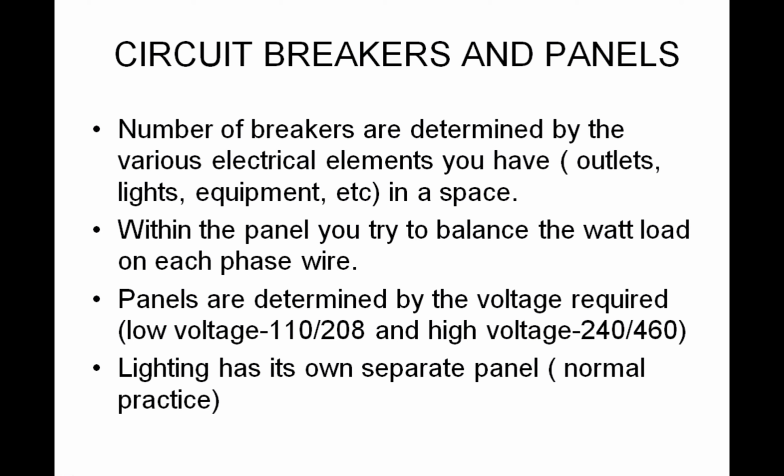And that's also so that if we need to work on equipment or systems, you're not working in the dark. If a system trips, like your HVAC system or your air conditioning system, and you have to go work on it or troubleshoot it, it's impossible to do if the same circuit contains your lighting, because then you have to use temporary lighting or bring in flashlights, and it's much harder to do. So it's always wise to keep lighting separate.